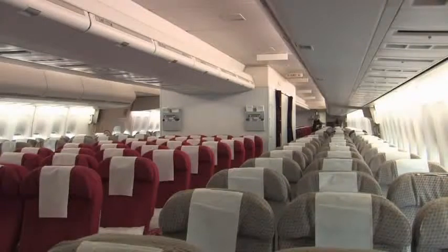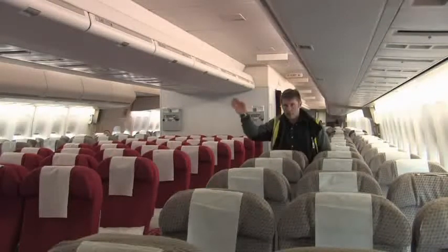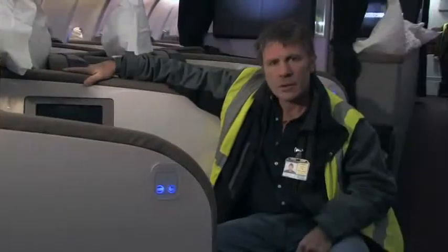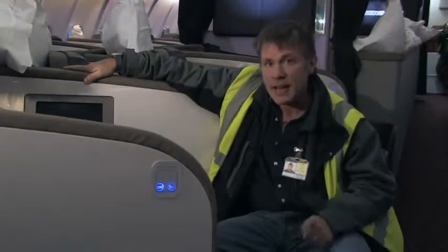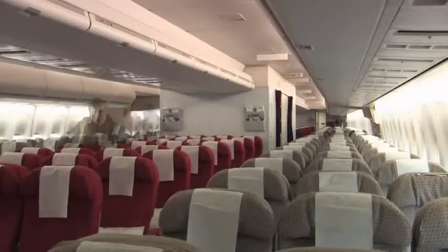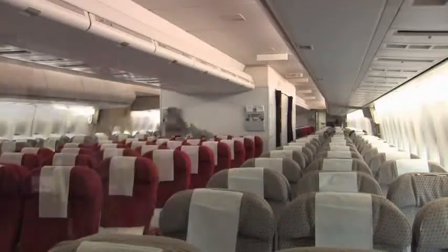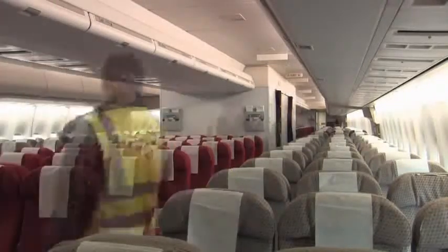As a passenger, my location on the aircraft can make a real difference to the aircraft's centre of gravity. In fact, I'm changing the centre of gravity on this Boeing 747 simply by walking up and down the aisle. But my seating position can also make a real difference. For example, here, or here, or here. Just remember, on average, every person sitting on board an aircraft weighs the equivalent of 7 passenger bags down in the hold. So, from a cabin crew perspective, whether you're operating an allocated or free seating flight, be aware of passengers playing musical chairs after the doors have been closed. If they move, the C of G will change.